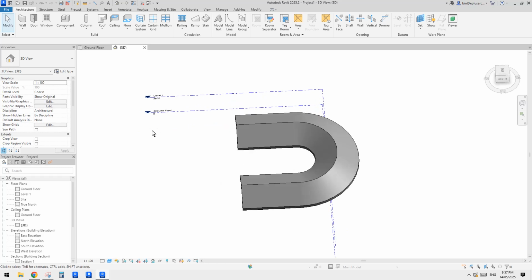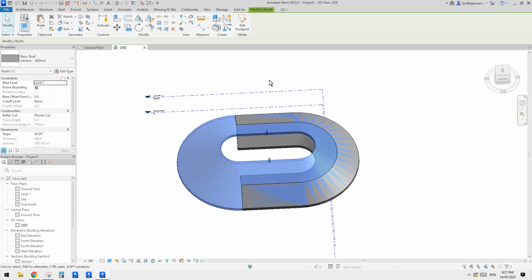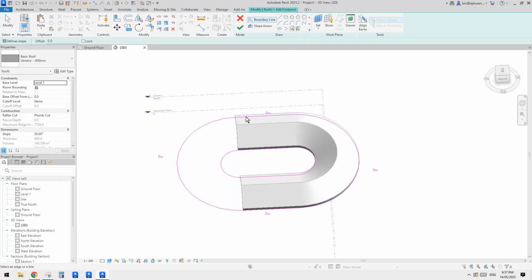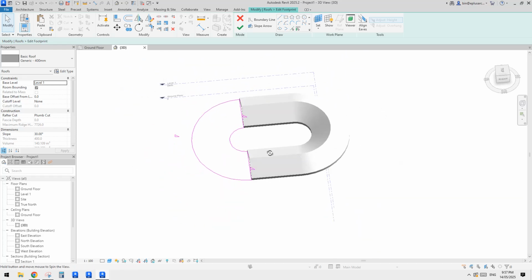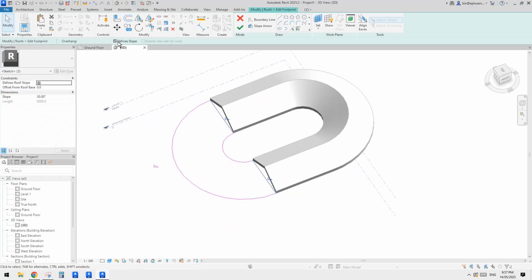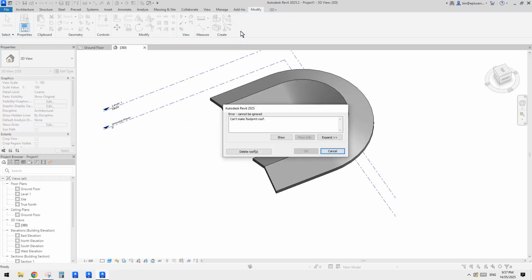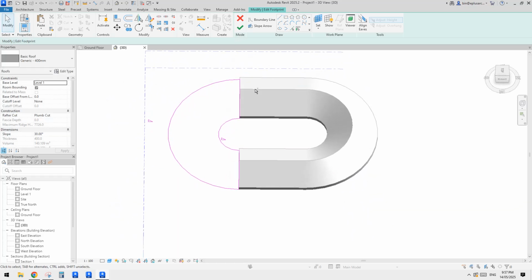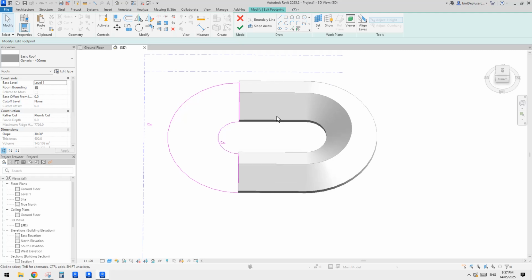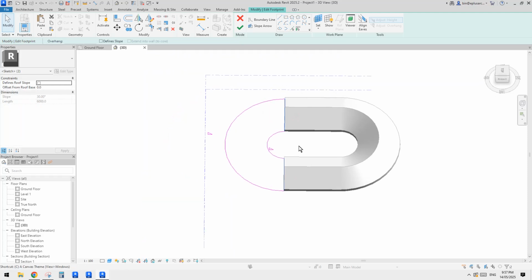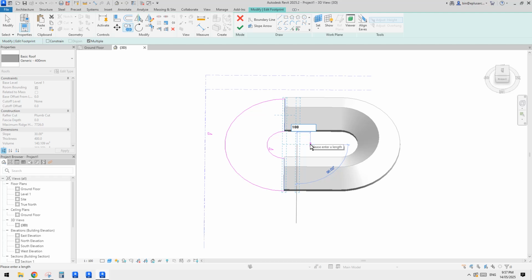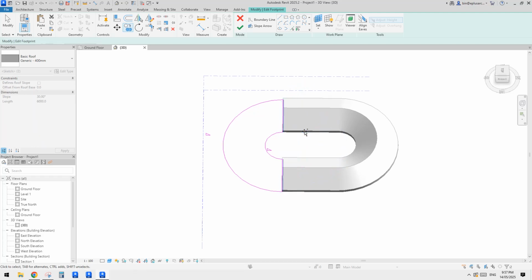So it works. Which means if we just paste in the same place, edit footprint, and I'll just pick that line, trim. Oh, sorry, we don't need to trim, because it's already the end of that arc. And also let's just untick the define slope and tick define slope on this one. Doesn't work. So that's fine. I guess we probably just need a little bit of straight line here. So maybe I'll just CC copy it by 1 meter, or even just in the middle. Yeah, that's fine.